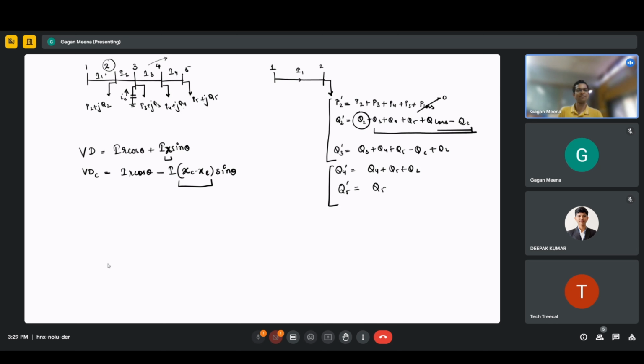And because of that, there can be voltage rise. So it will result in voltage boost at this particular bus. So if a series capacitor is connected here, bus 1, 2, 3, then V3 can be more than V2 because of this overcompensation.